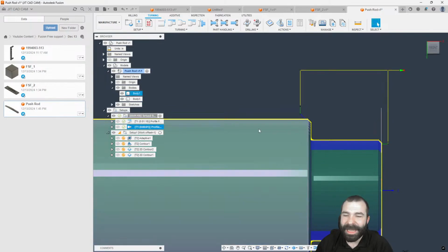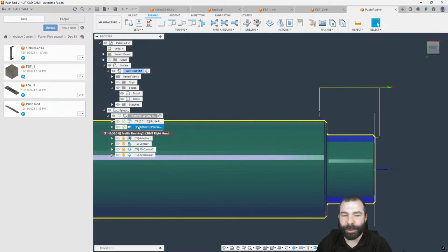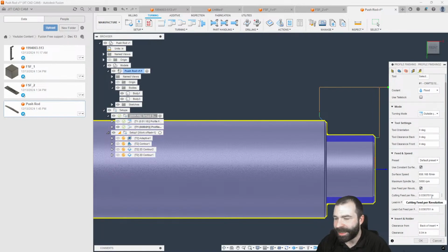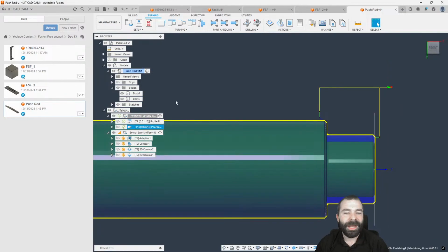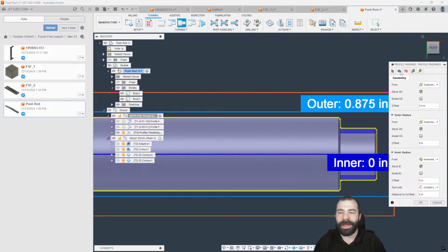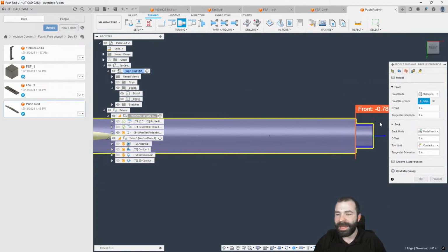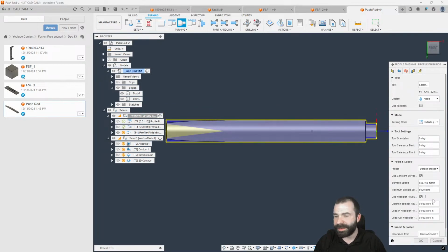But as you can see, I would have to take that tool path. There would be my first go. I don't have 2 sets of speeds and feeds on this tool, guys, but let's just say, what is this? A 40 thou feed per rev. And then I would make my second one. Of course, now we're going to go ahead and start with our selection for front. And then we're going to go all the way to the back. And maybe this time we're going to use, you know, a 20 thou rev, right?